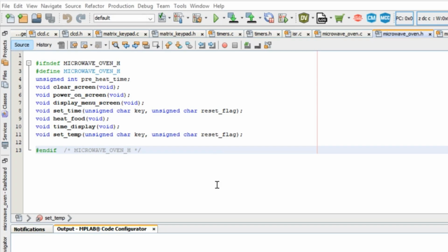One of the critical aspects of the microwave system is time setting. The user inputs the cooking time using the keypad, and the code ensures that the entered digits are correctly placed in the minutes and in the seconds format. The system also additionally provides the user the ability to clear and confirm the input values using the star and hash buttons. So once the time is confirmed, the microwave starts operation. It activates the fan and the timer.